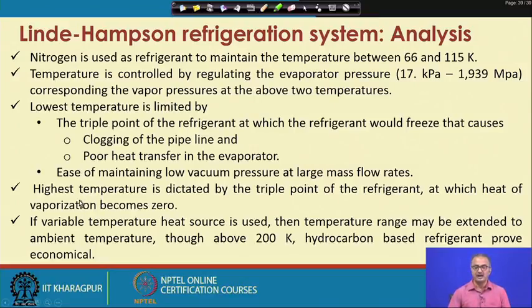And then the highest temperature is dictated by the critical point. Why? Because as I told you, we cannot liquefy a gas above the critical point. So we cannot move beyond it. We should always stay within the critical point of the particular fluid. And then, as I said, we are using an isothermal temperature source, but there could be a variable temperature heat source also.